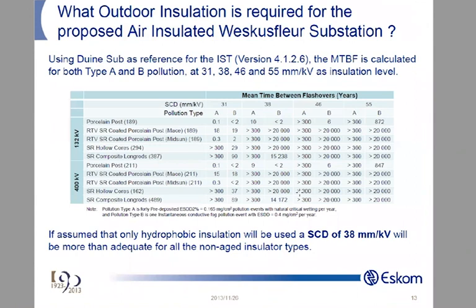Right, sir? These RTV coatings, how long do they last? Well, we've got more than 20 years of experience with coatings locally. I've evaluated most of them in relation to one another. There are very poor coatings, terrible ones. I've got ones that have flashed over 4 times in 1 year in my test station. I've got other ones that haven't flashed over to date. So, yes, they work, and no, they don't work. It depends on the coating.